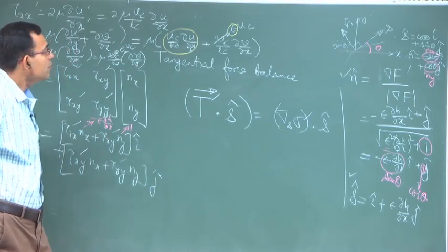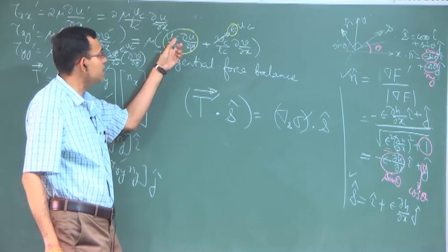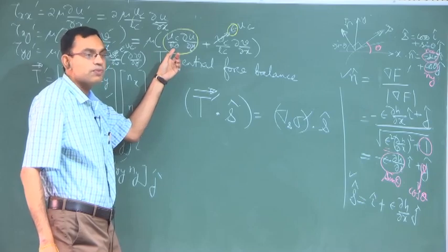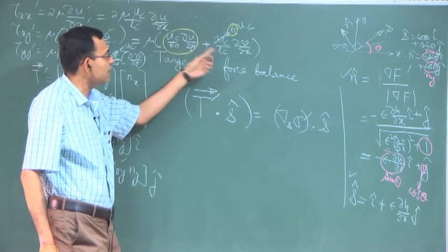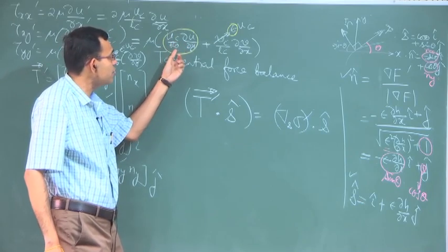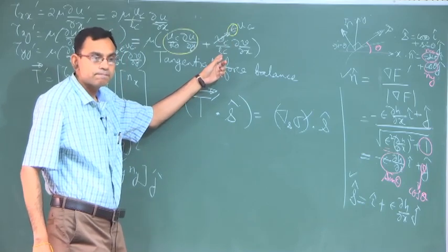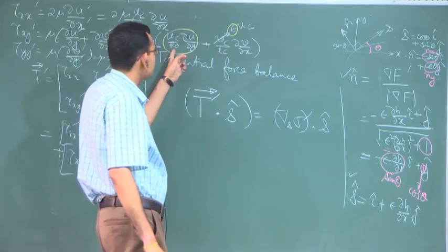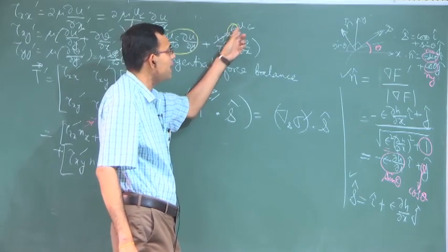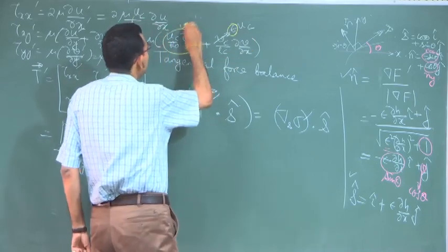So, this has a velocity by a small length, right. uc is the dominant velocity and this is the smaller length scale. Out of h naught and LC, h naught is smaller. So, uc by h naught will clearly dominate epsilon uc by LC, right, because uc by h naught will be greater than uc by LC and epsilon will make this term further less, right. So, this term will clearly dominate,